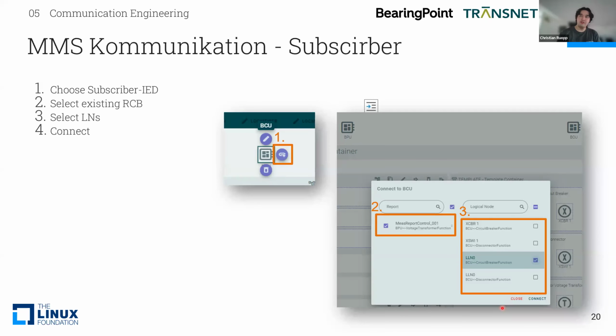So after publishing the data somewhere in the network, another IED has to subscribe to the data. Otherwise, this action would be pointless. So in the Substation plugin, we have to select the IED and then click this chain button to let the IED know it has to subscribe to something.